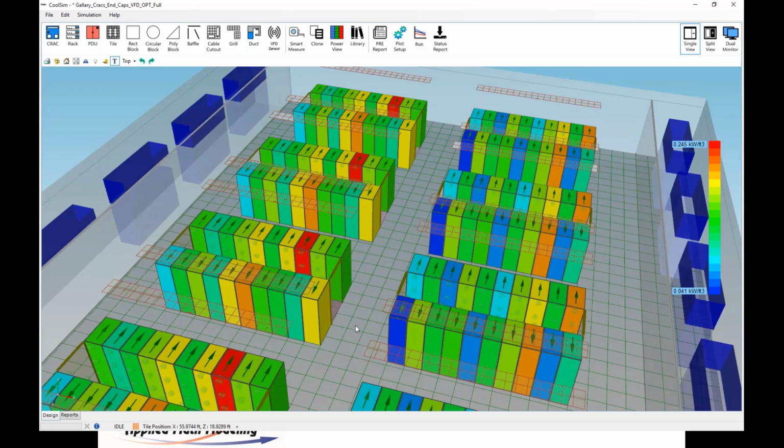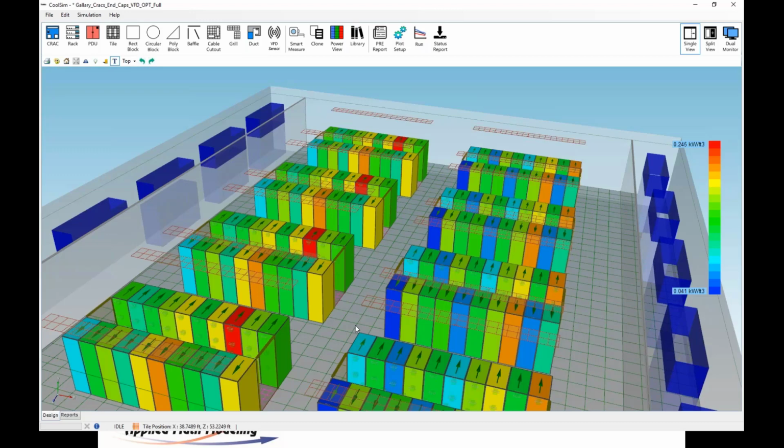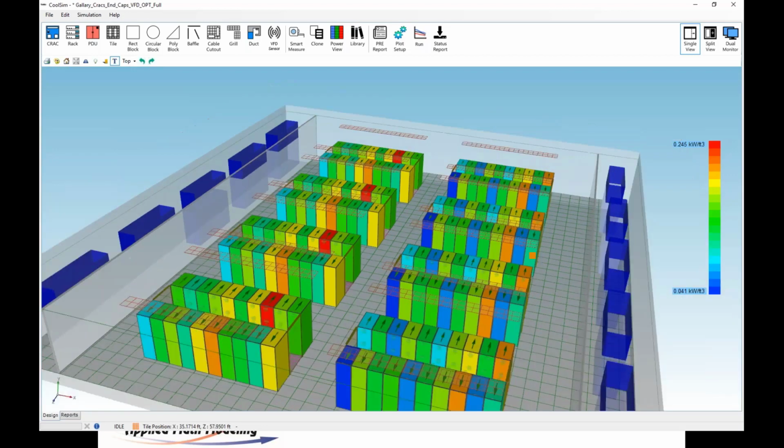So it is assuming that the racks are operating fairly perfectly with respect to leakage. So there's no leakage assumed in this model through those racks at the moment. You can always add it, but I did not assume it here because I'm trying to make another point. I've got the racks sitting on the floor with no leakage underneath them, and they're performing pretty well.